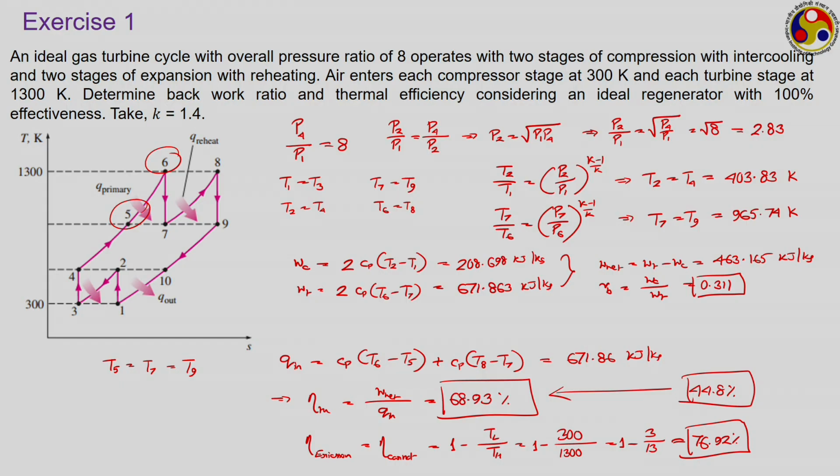With increasing the number of expansion and compression stages, we can have at most a further 8% gain, which may not be worthwhile in most practical scenarios, considering the complexity required to have so many stages and also the space requirement for this. So, generally it is restricted only to 2 or 3 stages of compression and expansion.